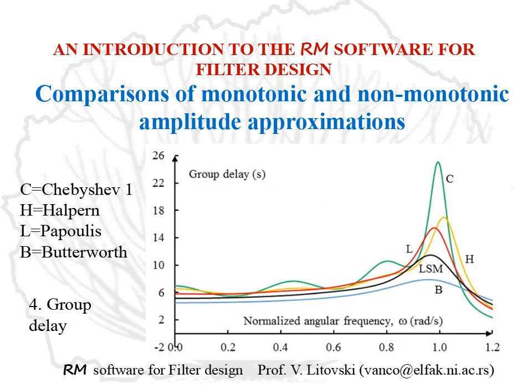That is mapped into the group delay characteristic, and we can see that the Chebyshev filters, as already shown, have a dramatic change of the group delay in the passband, while the monotonic ones may be considered advantageous, especially the LSM, which is much more selective than the Butterworth, which has a much smaller, incomparably smaller attenuation in the passband than any one of the rest of the classes, and of course it has an acceptable selectivity which is larger than the Butterworth one.